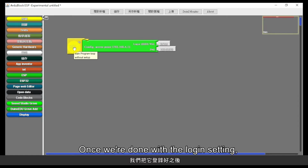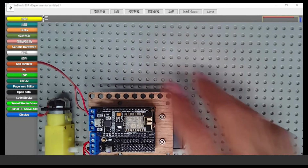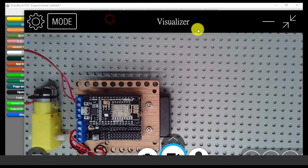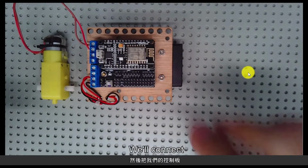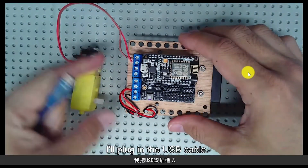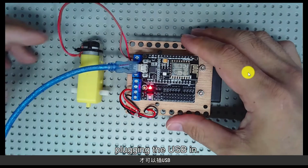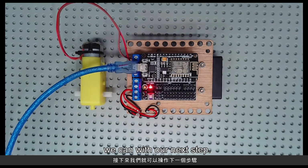Once we're done with the login setting, we'll upload this. We'll grab our controller board and connect it. I'll plug in the USB cable. Remember that the power must be turned on before plugging the USB in. After plugging it in, we can go on with our next step.